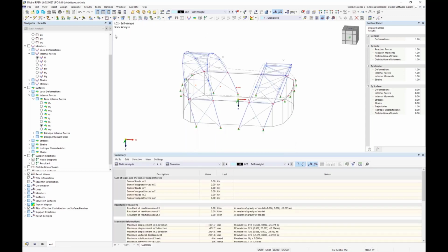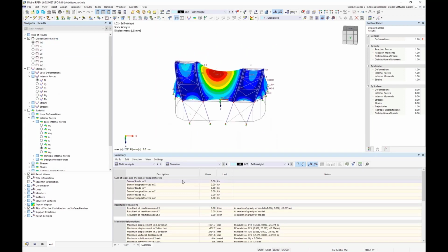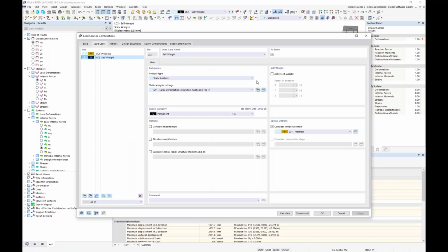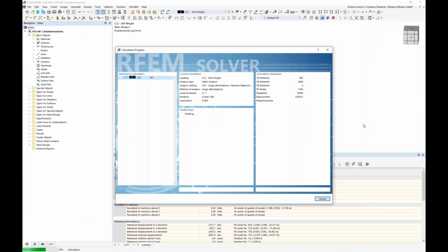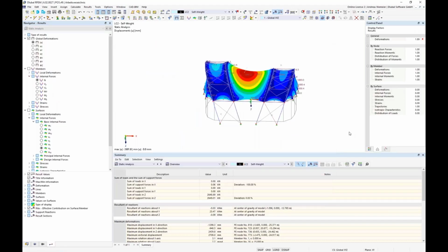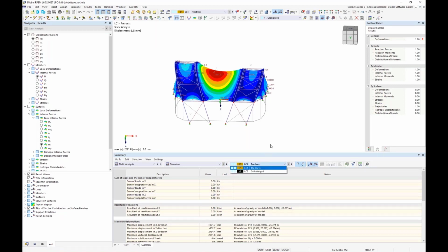And if we take a look, you can check it quite easily. Here we can, of course, activate results, but if you take a look here at pre-stress, you see, oh, I forgot something. Yeah, you see this is 0 load in C, and the same for self weight, because we have no forces in this load case. We have to activate something. We have to activate the self weight. And now let's run it again. And now let's hope that this sum in C contains these forces. And now load case 2 has these forces and load case 1 not. So this is maybe good for a plausibility check.